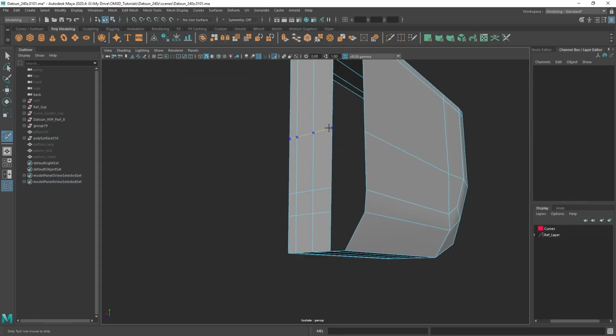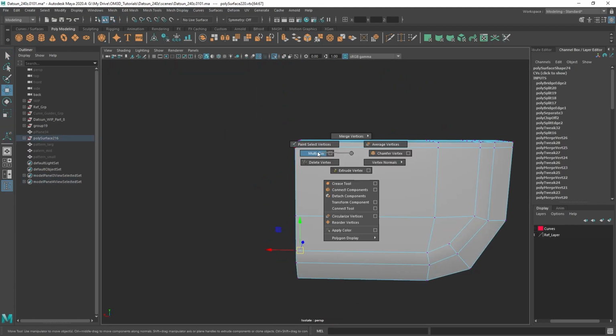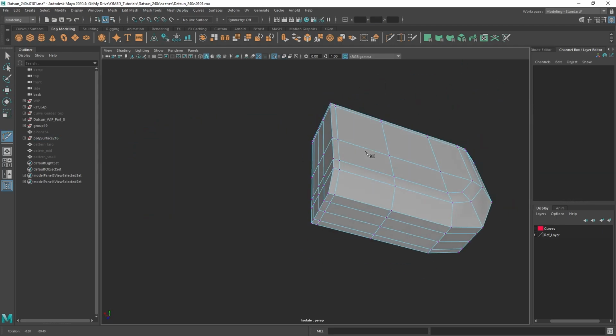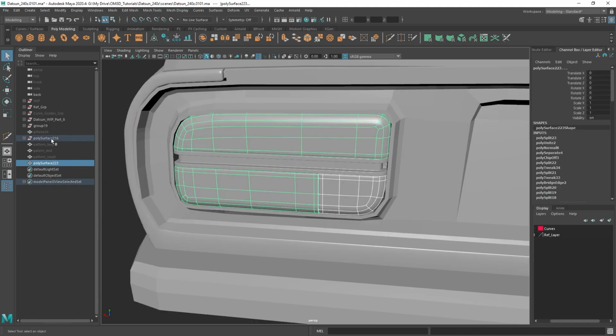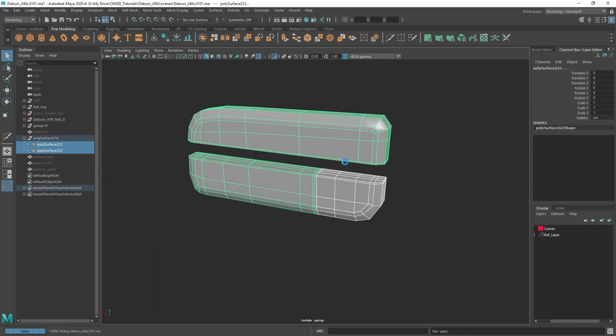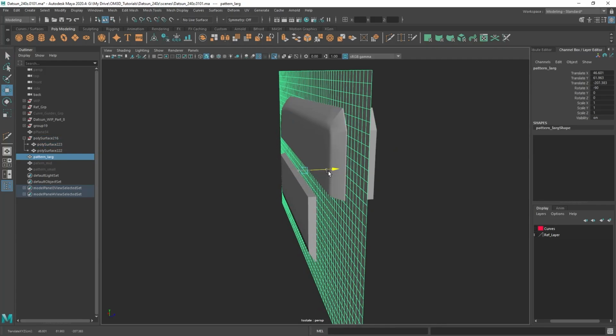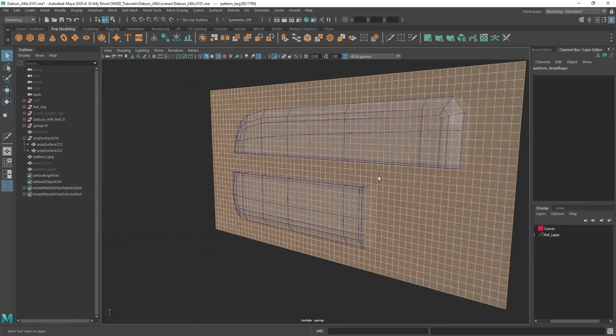So I need to break out the reverse light, so I need to do that before going any further. Clean up the geometry, add thickness, duplicate that face, and then reverse normal, add it to the other side. So I've been doing that over and over. It's just a nice way to get good, clean seam lines.